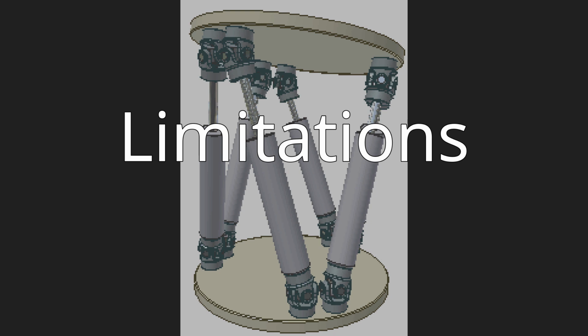If the input ends abruptly, then the high-pass specific force response will initially cancel out the specific force associated with the tilt, but only for a brief time before the restricted simulator displacement prohibits translational acceleration of the simulator. If the tilt is removed quickly, then a tilt coordination angular rate false cue will occur. If not, the remaining tilt will create a sensation of acceleration, called a tilt coordination remnant false cue.